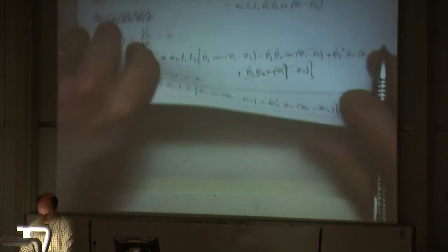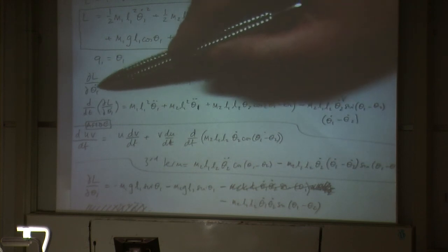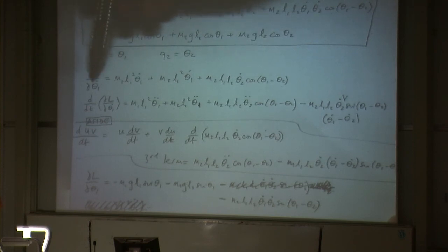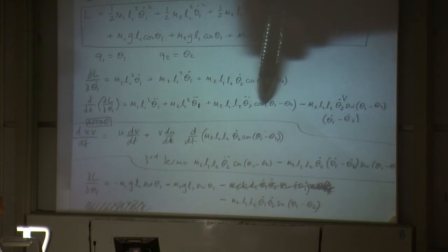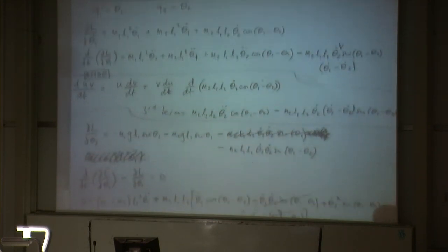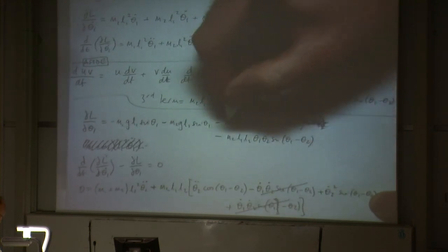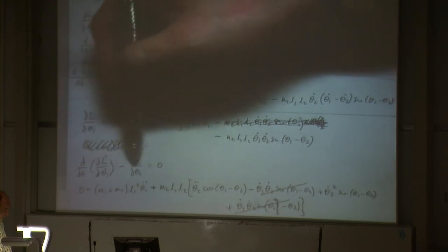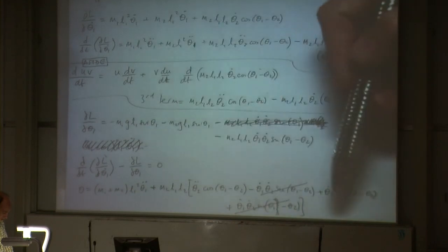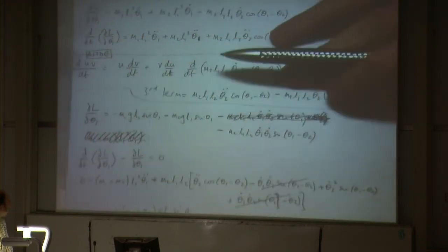Now, let's just go through the process again quickly. We find the Lagrangian. We then go through, we find dL over d theta 1 dot, which gives us this expression. You then have to take the time derivative of this term, d over dt of this term, which gives us this expression. This was an aside just showing you how I got these last two terms. So those two terms, stick them into there. We then have to find dL over d theta 1, which is this lot. Apologies about this mistake, but you have to include the theta 1 minus theta 2, I believe. Then this is Lagrange's equation when there's no damping and no force. Force is 0, R is 0, so then you stick this term minus this term into this equation, and that will give you your equation of motion, which is at the bottom.